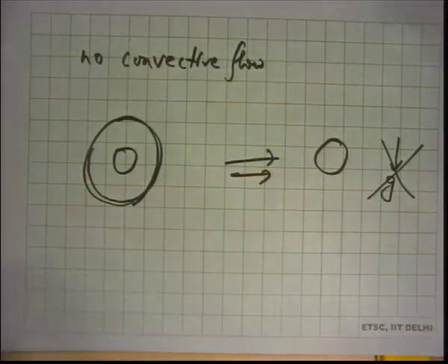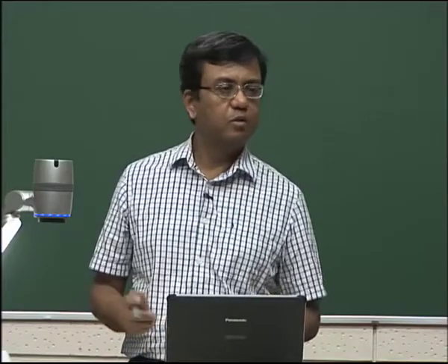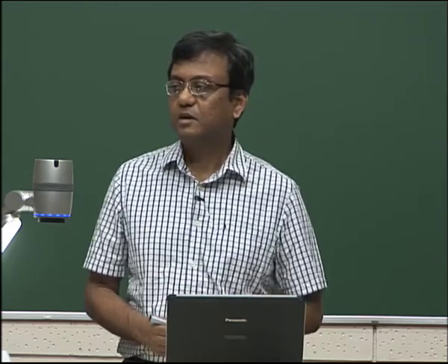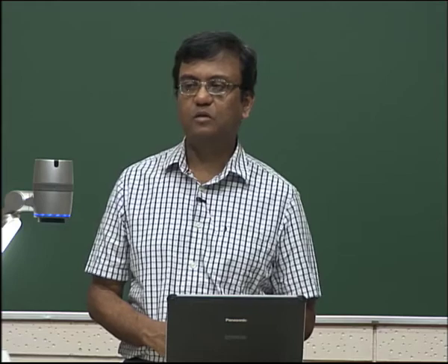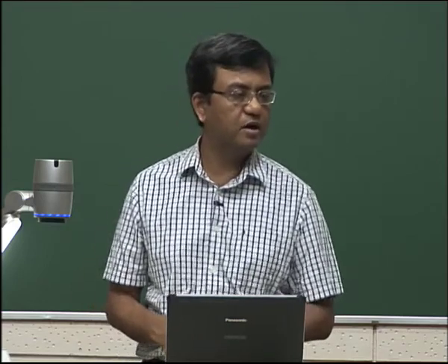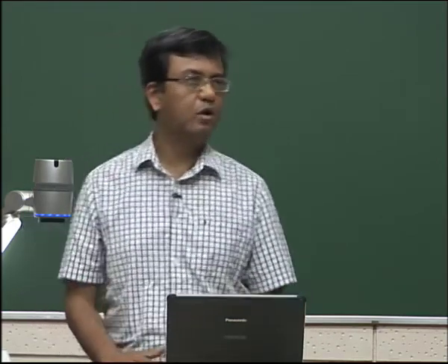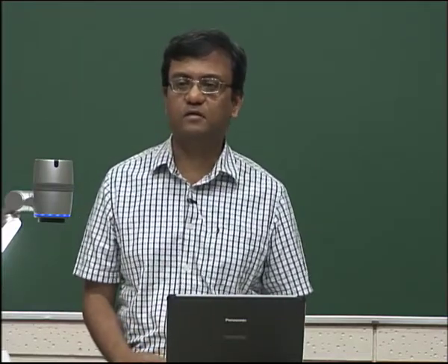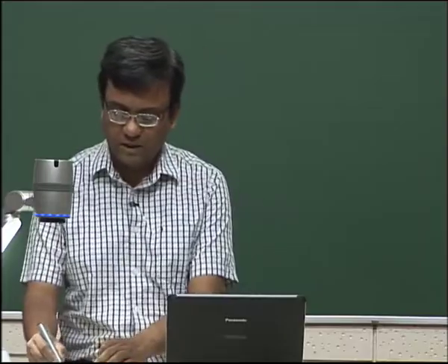And these were done, as I told you, in free fall facilities. So there's like a long tower sort of a situation where you prepare an instrumented box in which you put the droplet, you place the droplet on fibers, and then you have electrodes, and then you ignite the droplet, and then you just drop the box. Of course, it's not as simple as this. So it's a long vertical tunnel you can think of, and as it falls, you will get 1 or 2 seconds of what is known as microgravity time.